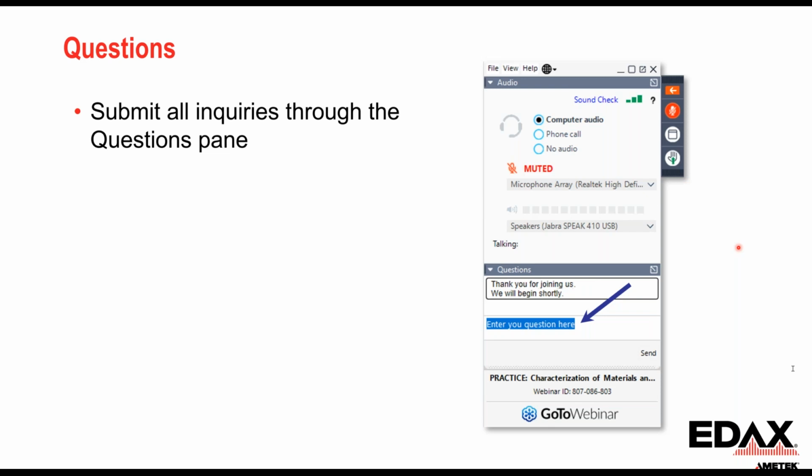But yes, it will be dependent on the sample, and it will also depend on whether you're doing traditional EBSD or using this detector for transmission EBSD or transmission Kikuchi diffraction. We've done step sizes at 1 to 2 nanometers on specimens where it's appropriate, but often your step size selection is really sample dependent.